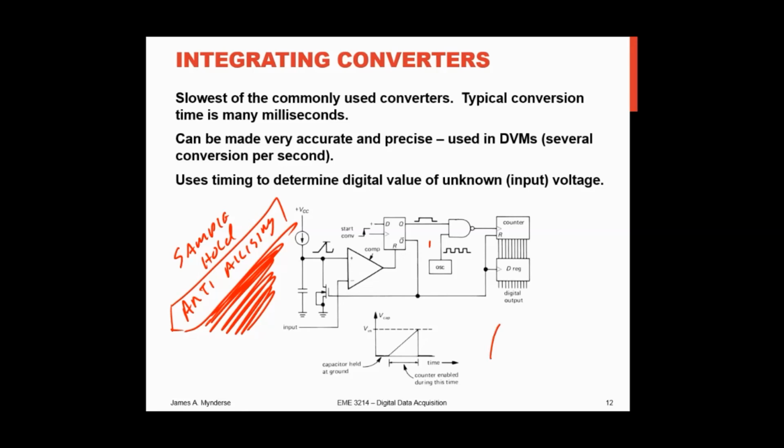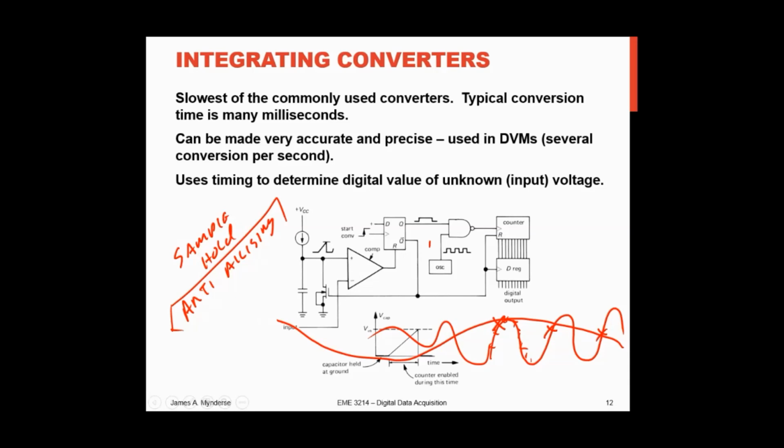Basically, if I have a noise frequency here, and if I sample it quickly, I get a pretty good representation. But if I sample it infrequently, say I sample it here, and I sample it here, and I sample it here, and I have to go backwards a bit, what I will end up with is a low frequency signal in my digital world that didn't exist, right?